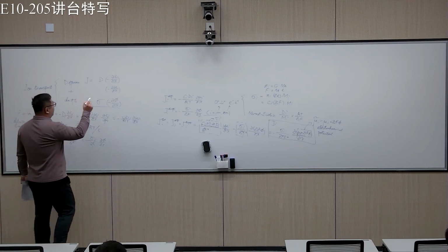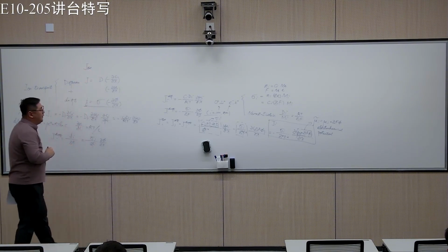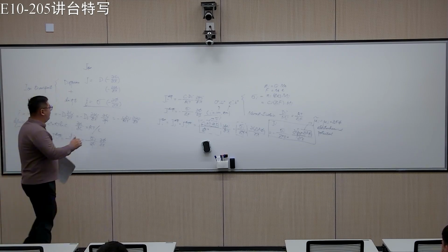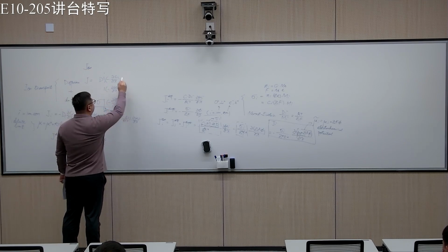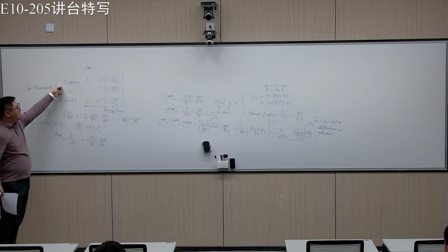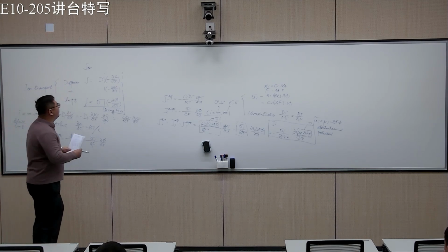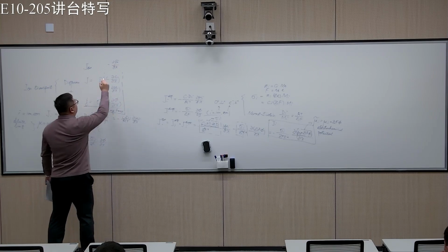If I say this is J total, which means we consider both diffusion and drift, then we know that this part is the driving force. If we have both diffusion, which is a concentration or chemical potential gradient, and drift, which means an electrostatic potential gradient, then the real driving force will be the gradient of the electrochemical potential.